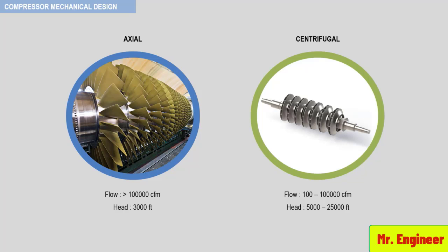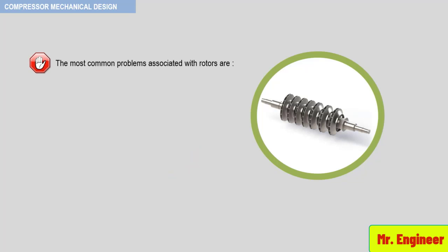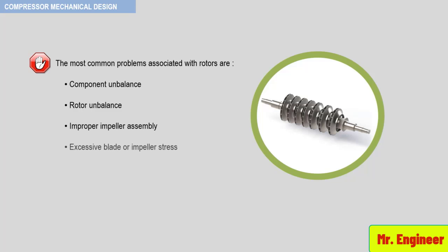The most common problems associated with rotors are component unbalance, rotor unbalance caused by improper impeller assembly, excessive blade or impeller stress, and rotor system natural frequencies. These topics will of course be discussed in detail later in this course.